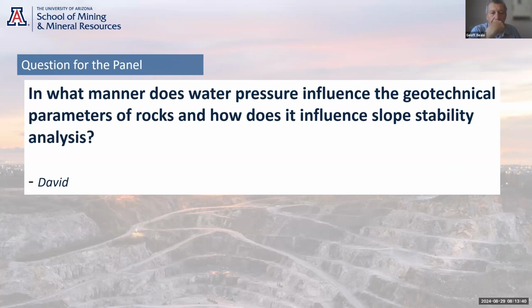It applies also to a porous medium. So if you can just imagine the sand grains, which are all compressed because of the weight of material above them, and the frictional resistance within that sand occurs because the grains of sand lock together and create a frictional resistance or a shear strength. So now you put water between those grains of sand, it tends to push those grains of sand apart. It has less frictional resistance and therefore less shear strength.